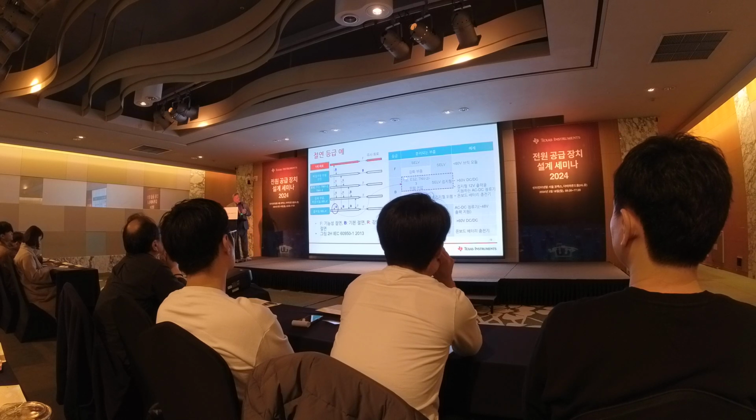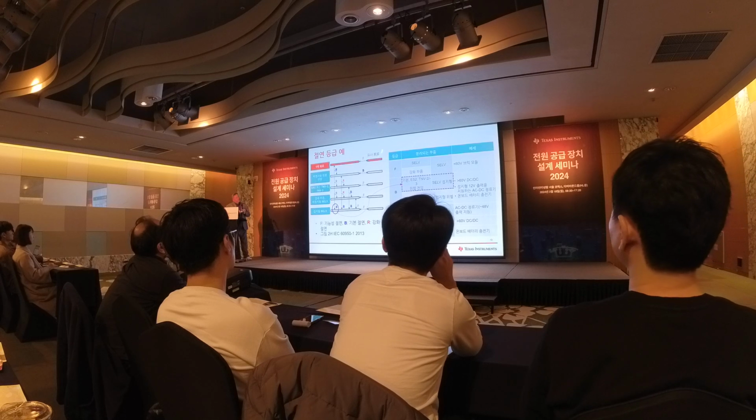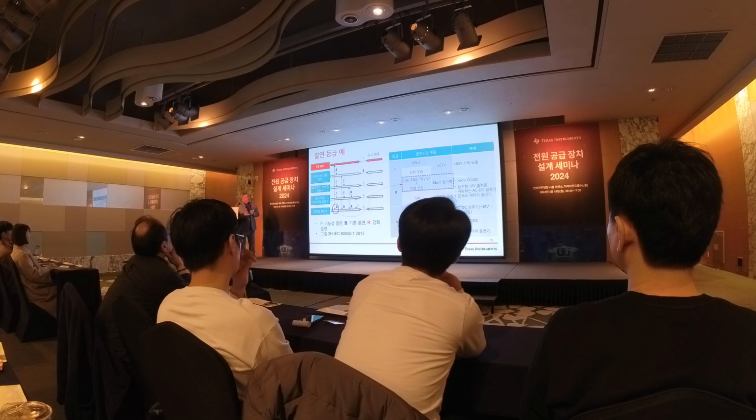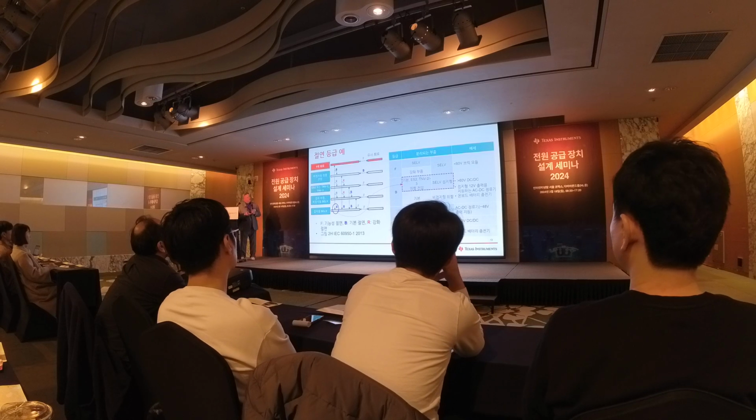So for functional insulation, if we're going between safety extra low voltage and safety extra low voltage, like from here to here, we just need to have functional insulation. That's, again, just to make sure that the circuit is operating correctly. If we have less than 60 volts, also, that's functional insulation.